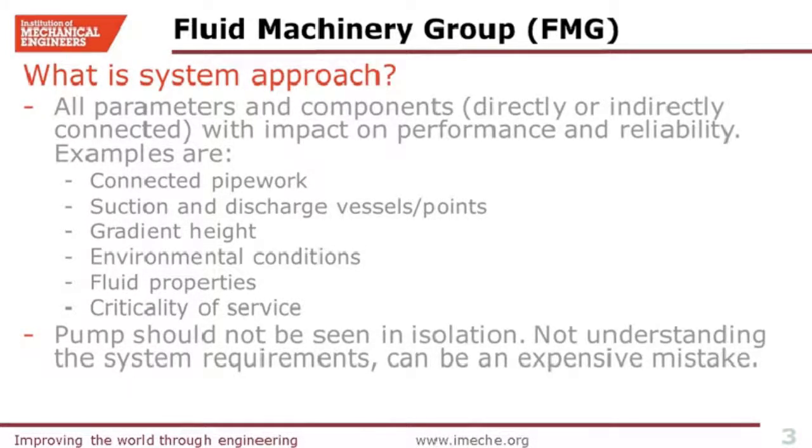So all these parameters, variables, components, which directly or indirectly impact the performance and reliability of the pump, we call them pumping system. Just to name a few, for example, connected pipework, which is the focus of today's webinar, condition of suction and discharge points in terms of pressure, height, temperature, the physical height differences between pump and, for example, suction reservoir or delivery point.